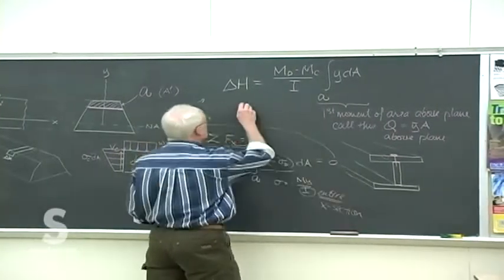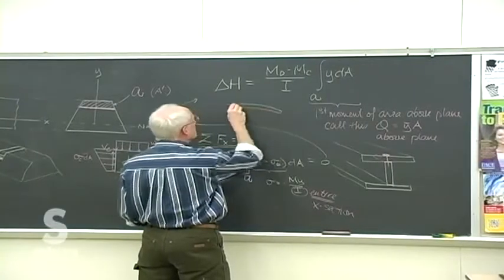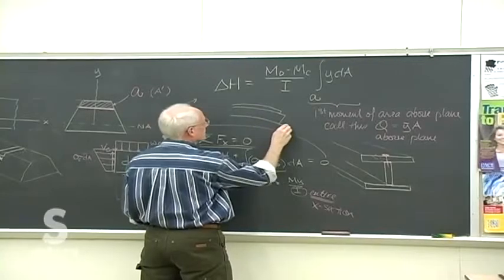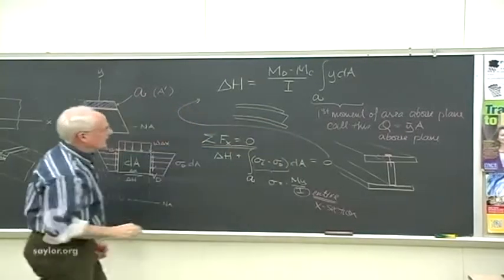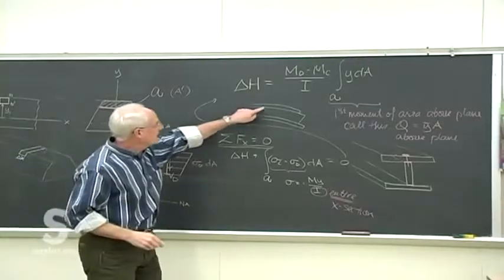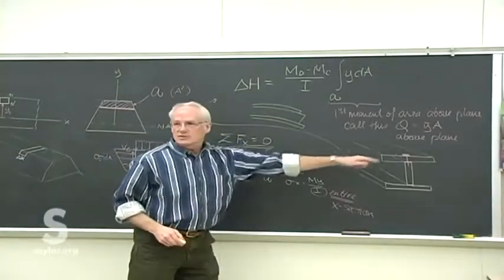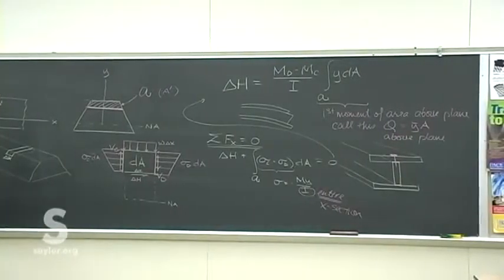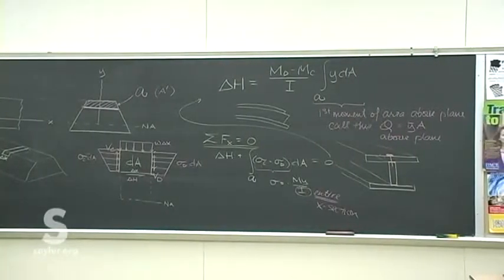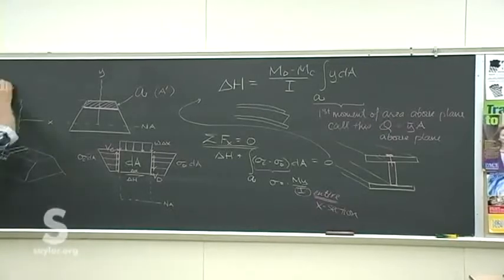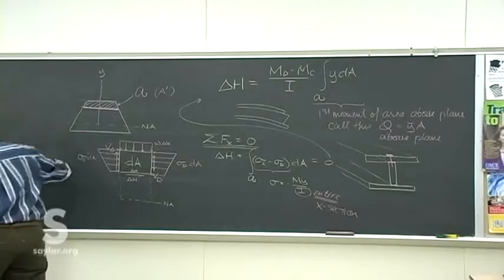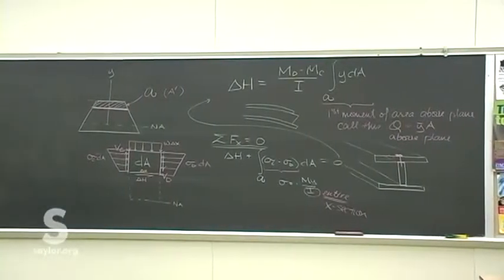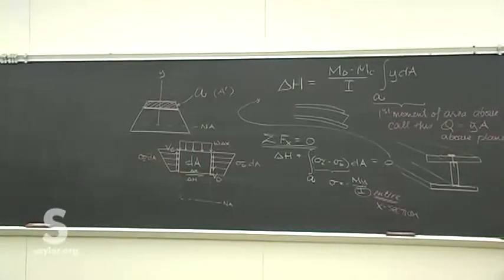If loaded, you wouldn't want the beam to do what we showed it doing with the earlier illustration. You wouldn't want these planes shifting off of each other, which is why you can glue them and screw them, to make sure they stay in direct and intimate contact to maintain the integrity of the beam. So we're almost done with this. We almost have it put together.